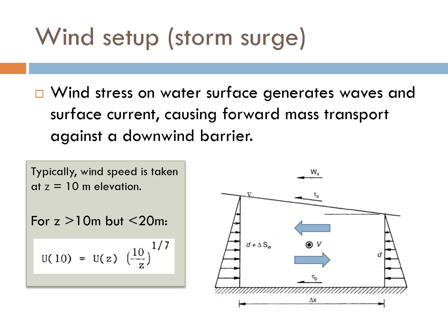and as a result of that we have a higher water elevation on the downwind direction, pretty much like what we see in the seiche, except that wind setup is not oscillatory. Wind setup will produce a setup like this as long as the wind action continues to apply the shear stress on the surface of the water, and if the wind ceases, then the wind setup will diminish back to the original condition again.